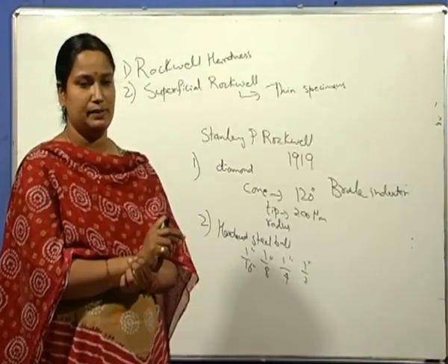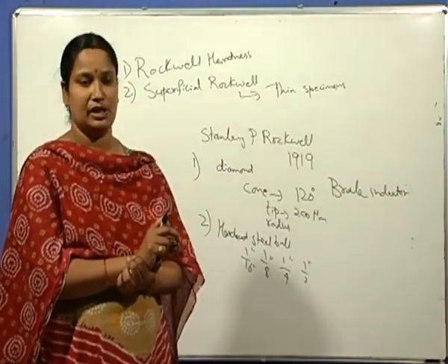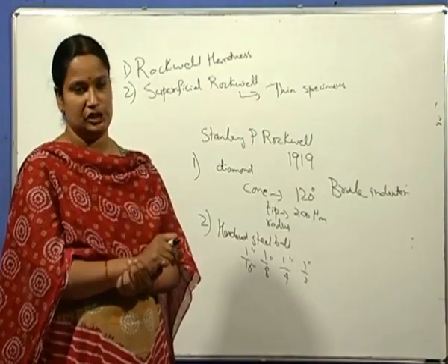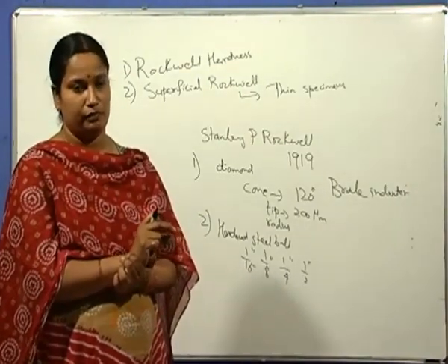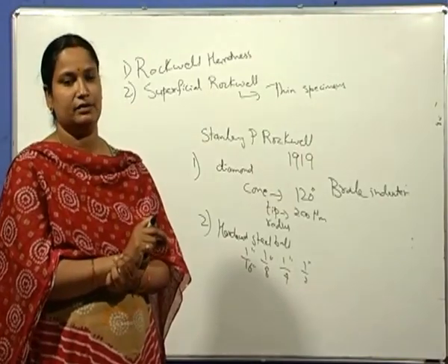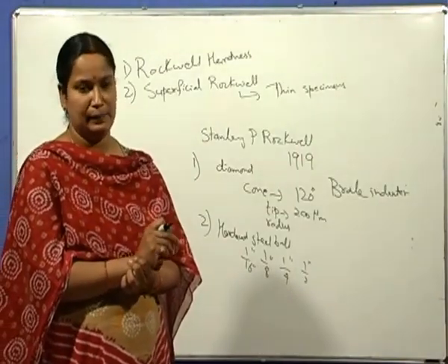The hardness number is obtained by measuring the depth of indentation, the difference in depth of penetration of the indenter from the two load applications.